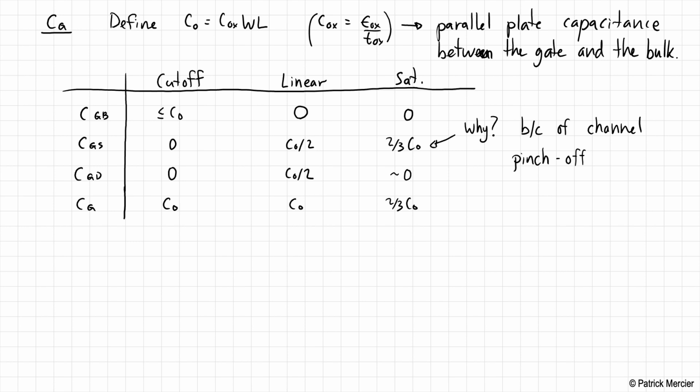Okay, so what we've described so far is what we call parasitic capacitance, or in other words, capacitance that exists in the device, even if the device were perfectly fabricated. Now, there's also something called overlap capacitance, which occurs due to fabrication imperfections. Okay, and so what we mean here is that the gate overlaps the source and drain regions by a length called LOV.